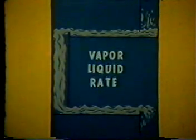However, there is a certain vapor and liquid rate beyond which a tray can no longer be operated, regardless of the hardware design improvement or increase in tray spacing. This phenomenon is called flooding by system limitation.